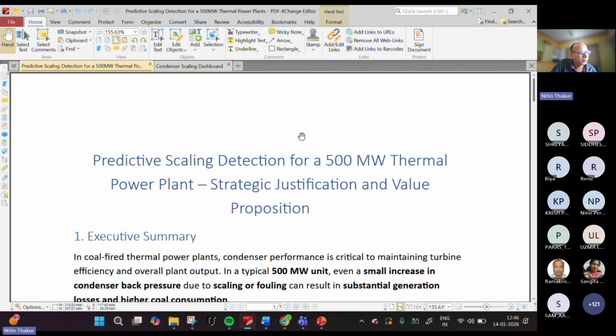I don't remember the exact word right now, but it can even measure down to the active ingredient of the anti-scalant. If the scaling increases, this active ingredient will get consumed, and based on that, the dosing pump of the anti-scalant will go up and down. So it is actually done to that level. I think Nalco is doing that.